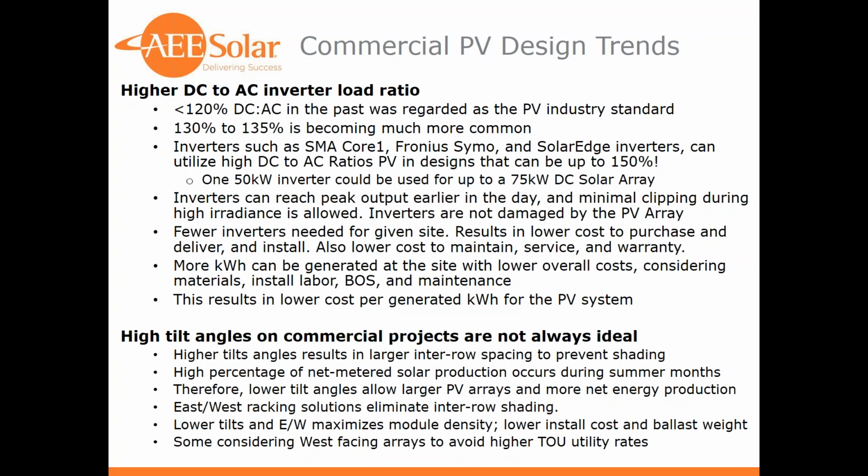And the benefit there is that your inverters reach peak output earlier in the day, and we see minimal clipping during higher irradiance, and we generally allow that. And the inverters are not damaged by this higher PV array power. So anyway, that results in lower costs per generated kilowatt hour, and that's what your customers are really looking for.